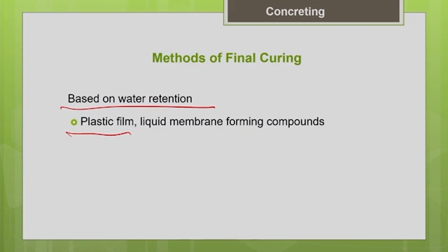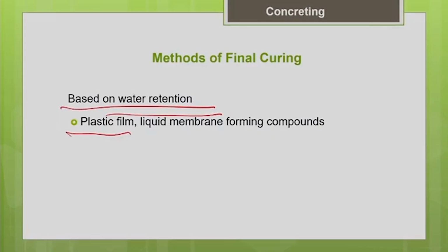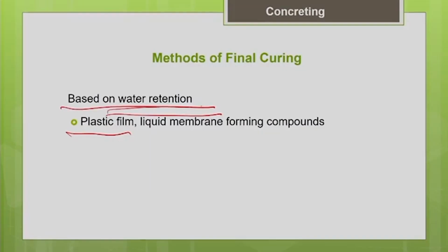This is very commonly followed in places where sufficient water is not available for curing, where there is water scarcity, and in some structural elements which are not easily accessible, where it is not possible to continuously apply water curing. In that case you can go for water retention methods. It depends upon the accessibility of the structural elements for the water application. In some cases we have to go for water retention only, because it is not possible to continuously supply water for the curing.